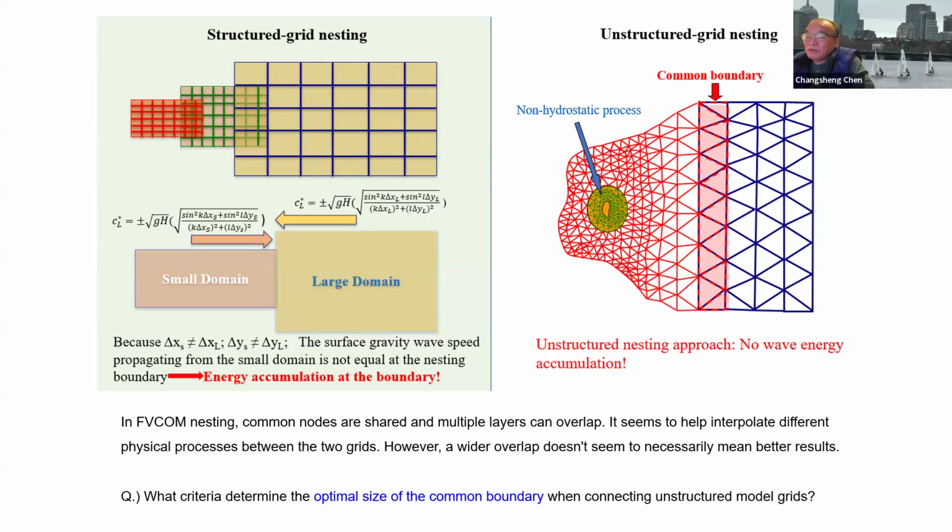One is coarse resolution. Another is that they made the horizontal diffusion very big. Most coastal regions use horizontal diffusion around 10 to the power of -2 meters squared per second. You know how much they used? 10 to the power of 7. That means they can diffuse water very quickly to every place they want. So for a lot of models, if you don't know much physics, you can really be misled.